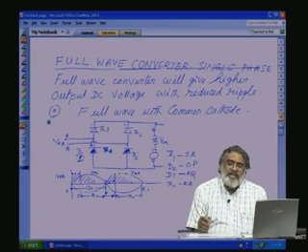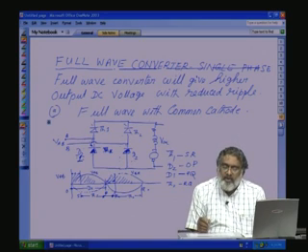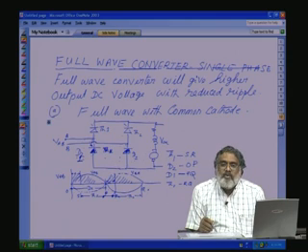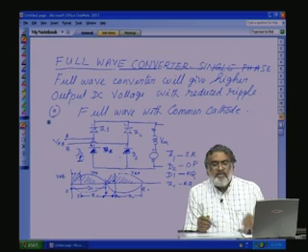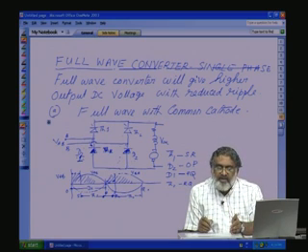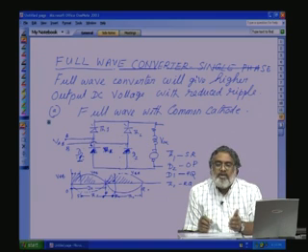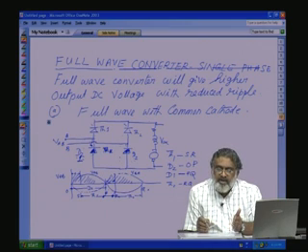So what is the disadvantage here? We lose control. The moment we lose control, the output should disappear. But here we lose control while the power converter is still supplying power to the load. So how to avoid that? If something fails, the converter should conduct only till the inductive energy is there, then slowly come back to zero. That's the best way. The system should automatically come to a stop.